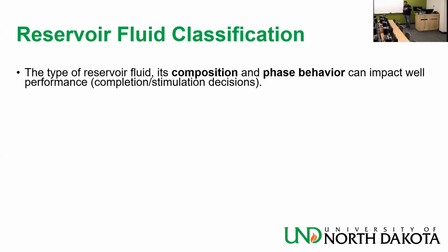If you go to a rig in America, there is a sort of a stand as you enter the rig, and it says if there is H2S danger. If it's a green flag, you are good. If it's a yellow flag, maybe some people who are nearby the rig need to wear a mask. If it's a red flag, everybody needs to wear a mask, and only qualified personnel should be there.